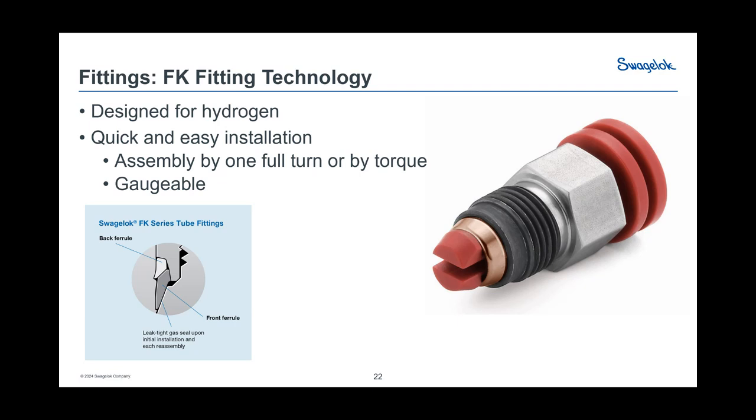Two other things you'll notice. You will notice that the front ferrule looks like a copperish pink color, almost red. We do that by playing with the thermal oxide layer on the part. We actually grow the clear oxide that's on the ferrule slightly, and then it interferes with light as it bounces through it. Turns it into a prism. So it turns out a reddish color.